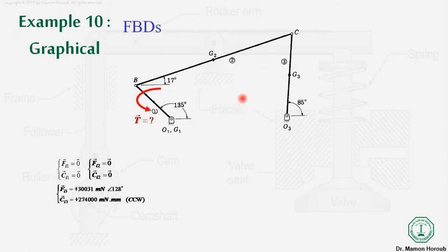If you remember, we discussed that as the reactive force is known, we will start from here. The reactive force is given to us, and also the reactive moment is given to us. So we have to find the value of the offset distance. When we apply the reactive force at that distance, it will cancel the effect of the reactive moment. So we need to find H3 such that the force times H3 is equal to the reactive moment. From that equation, we can calculate H3.